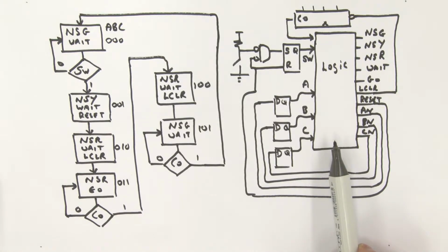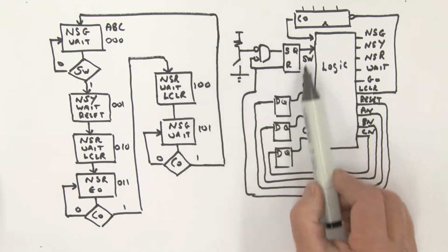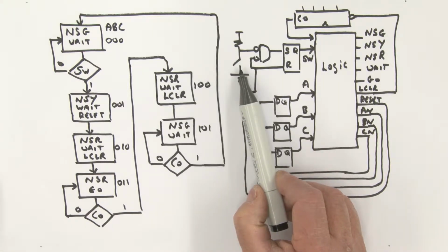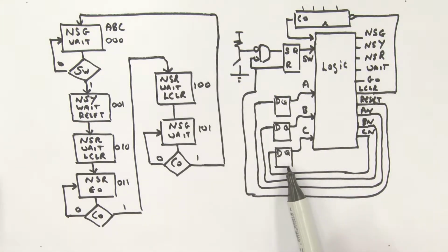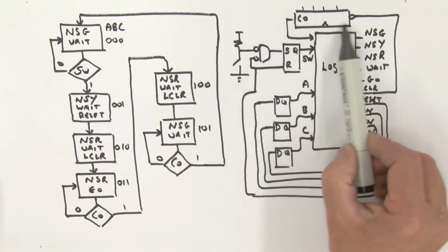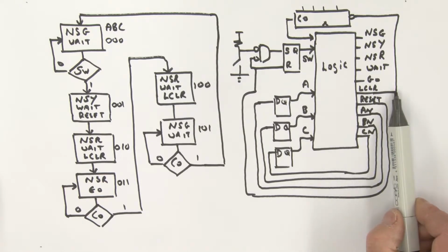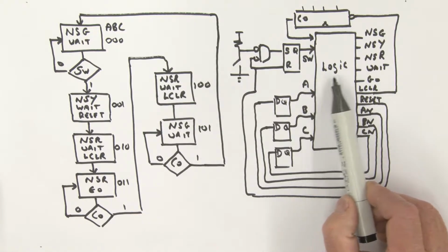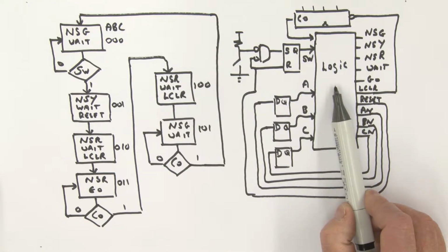Over here, you can see the block diagram of that system. We have the SR latch configuration here with the push button. This is a normally open push button, so on pushing it, this closes. We have our state variable flip-flops over here, and then our counter sitting up over here. And then our various light conditions here, the clear of the counter, the reset provided by the state machine, our next state outputs. Okay, so the issue is then, we need to be thinking about the logic over here and how we actually implement that logic.